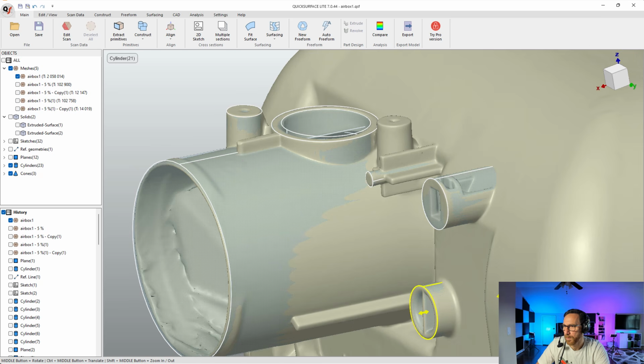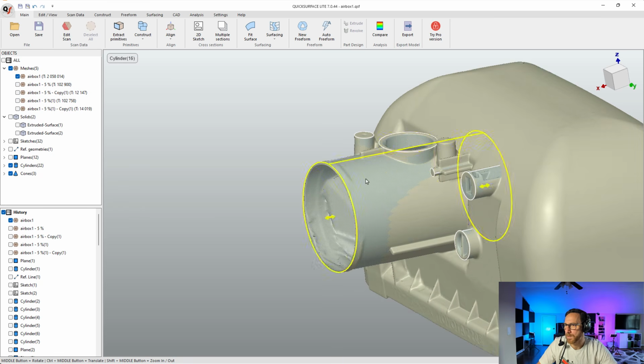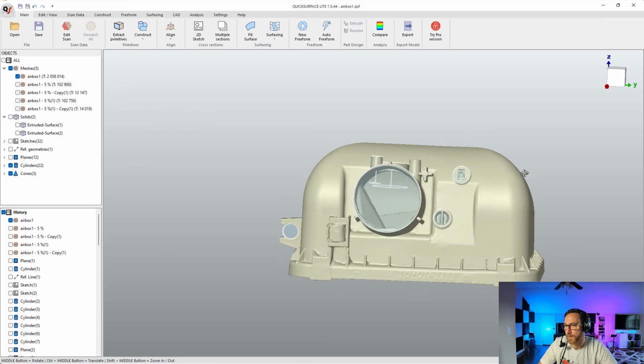We'll do this one. And then if we were to export this, so if we were to send this to Fusion, for example, then all of these would come in as solid bodies. We could join them together there, and then we could shell. So like the inside one we might not need if we're going to shell it, so I'll delete that one. But what we could do is take all of these, and all of these would be part of an export, and then in whatever CAD software we use, we could just combine them all together.